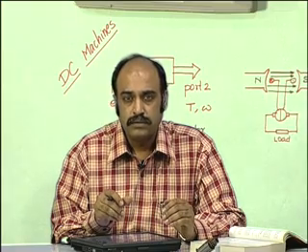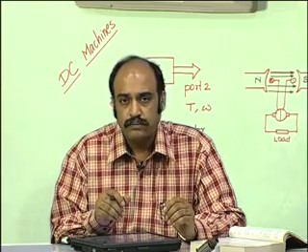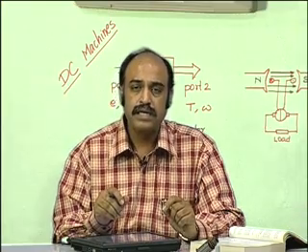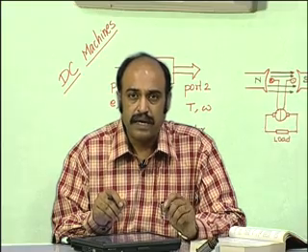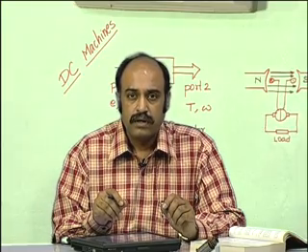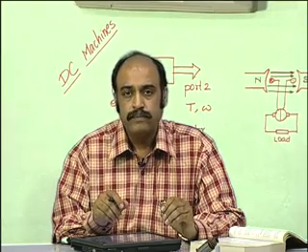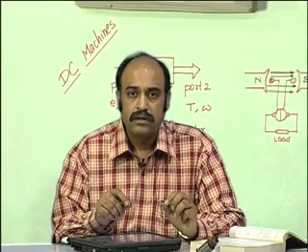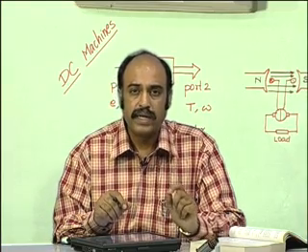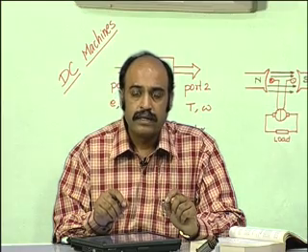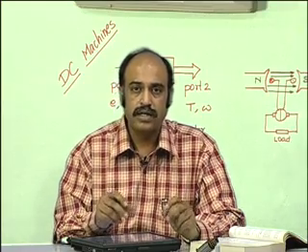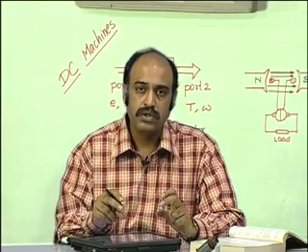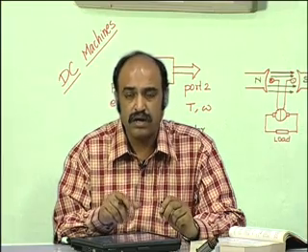In this session, I would like to point out that the operation principle of the DC machine is quite simple actually, and the number of coils, the number of slots are increased so that you get a twofold advantage. One is the increase in voltage across the brushes, because between the brushes there are now going to be more coils, and therefore the induced voltages of all these coils are going to add up and come across the brush voltage, as we saw in the discussion today.